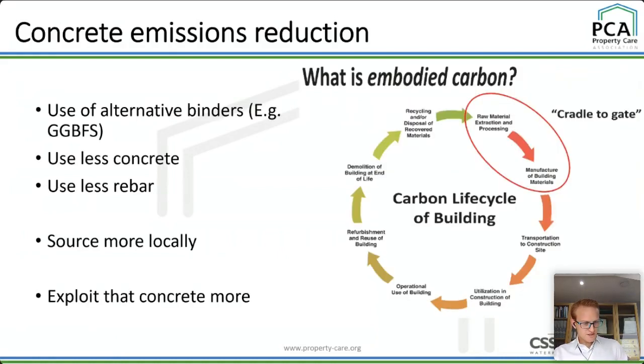So just going back to the sustainability thing then, if the Eurocode is saying thin sections need much tighter crack widths, then you might want to use a thicker section. Or if you're going with the thin section to get your crack widths down, you end up using a heck of a lot of reinforcement. So if the Eurocode leads to higher embodied carbon in your construction, would the responsible professional be saying, well, in the interest of sustainability, we need to at least consider using a waterproofing additive? So there's some things to think about there.